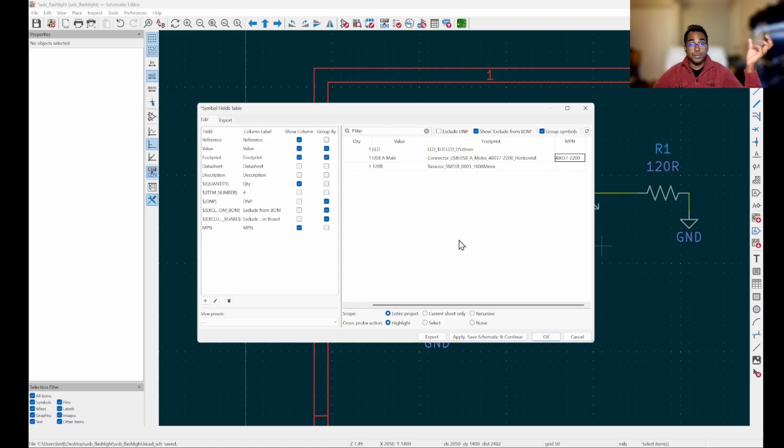So even though they do functionally the same thing, the pins might be spaced out a little bit more, or maybe they have an extra shielding pin or something. Basically, the Molex one that we designed this board for will not be directly substitutable with one that another manufacturer makes. So we have to include a part number indicating exactly which component we are using on this board.